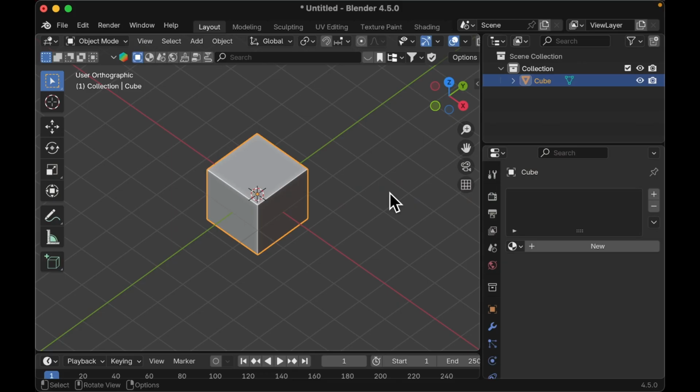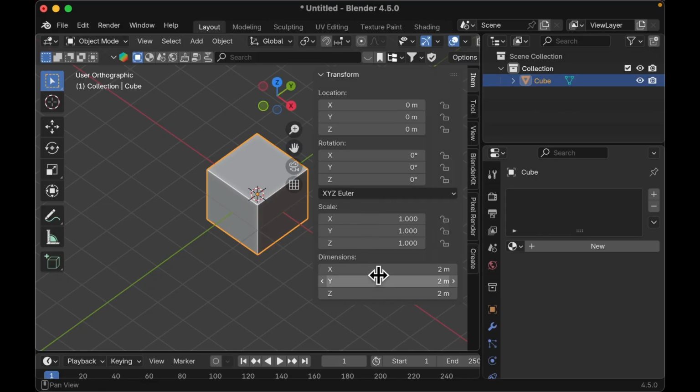So before we get started, we'd have to set up our file. A debit and credit card is not on the same scale as objects in Blender right now. So we'd have to create a world where we're only modeling small things. Right now, if you check on the dimensions panel here, this object is 2 meters on X, Y, and Z axis. That's literally taller than a real human. So we would have to reduce those scales drastically.